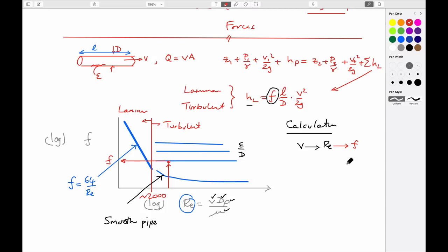And this would give you the ability now to calculate a revised velocity. And if the friction factor hadn't changed from your previous one, you'd actually recover the final velocity. If, for instance, you were somewhere on a regime that was different from that, you're able to move along it, then you just have to repeat this cycle. Once you've calculated a velocity, check the Reynolds number, see if the Reynolds number has changed from the previous one, and then if it has, you have to calculate a new friction factor and then go through the selection like that. And that's probably about it.